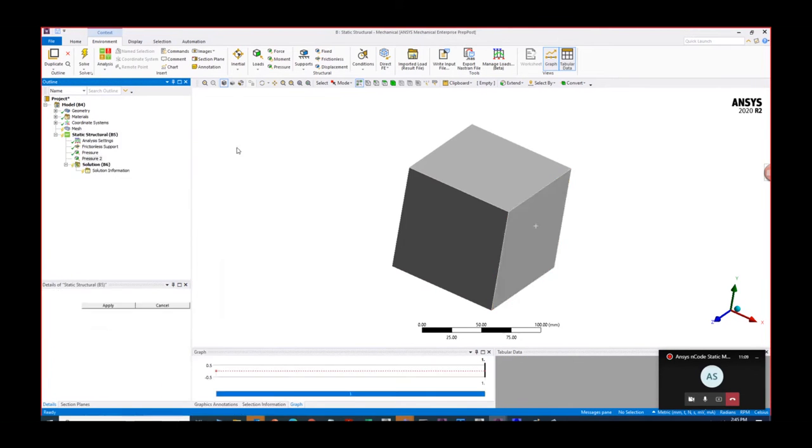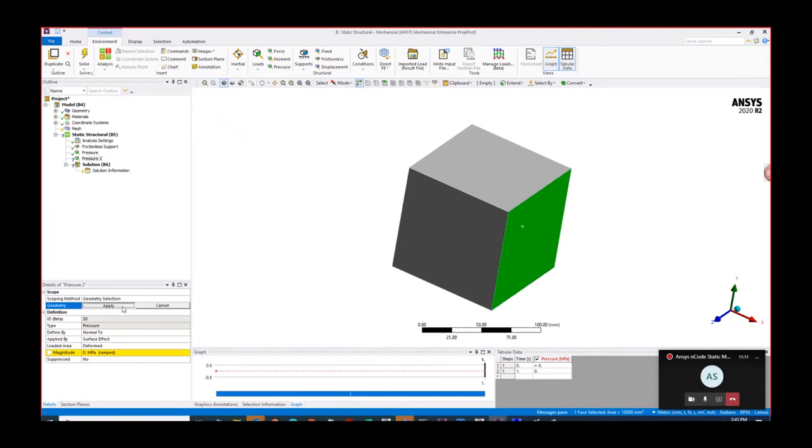I want to also apply a 200 MPa pressure, which is kind of fluctuating. Now, what would happen is that if we apply two pressures on the same location, one will supersede the other. Only this 200 is going to act, but we want both acting together. So the first pressure is applied through the surface effect element. The second pressure I'm not going to apply through surface effect elements, but I will apply directly on the FE model, so that both will exist.